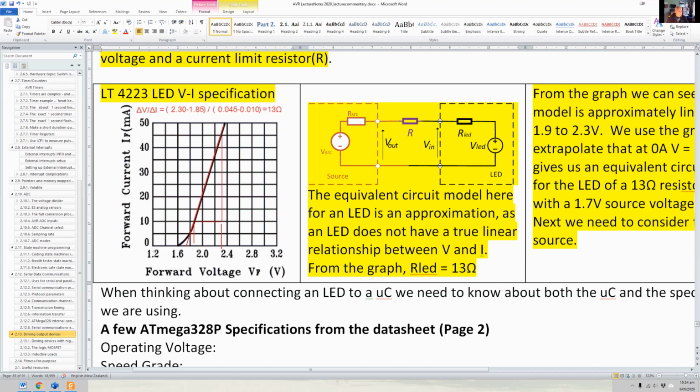So if I think of this as a very square characteristic, and I can do this because I'm really only interested in this part of the curve, which is linear-ish, then once we exceed 1.7 volts, this acts like a resistor. And there's the clue as to how we will model it. Once the input exceeds 1.7 volts, we can model this as a resistor of 13 ohms.